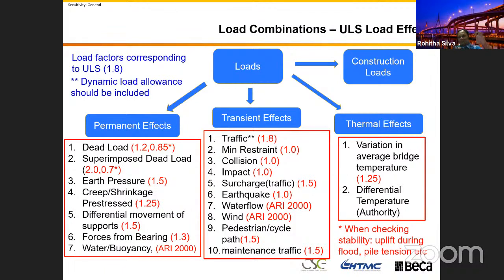These are the loads. That's why I warn you not to use the same thing. For example, for the traffic load in the Eurocode, you multiply by 1.35. The characteristic load models LM1 to LM4 defined in that code are in general multiplied by 1.35. Don't compare the codes, but this is the approach used in the Australian standard. So now you convert your loads from SLS to ULS.